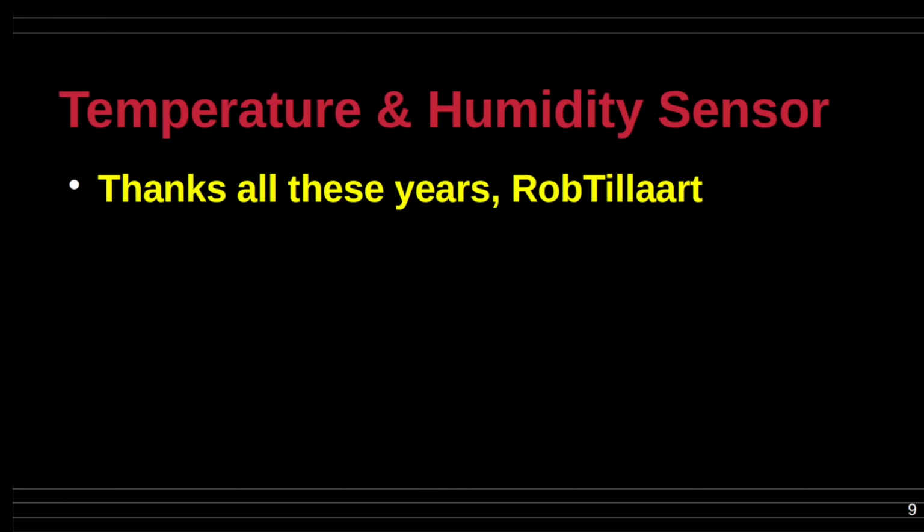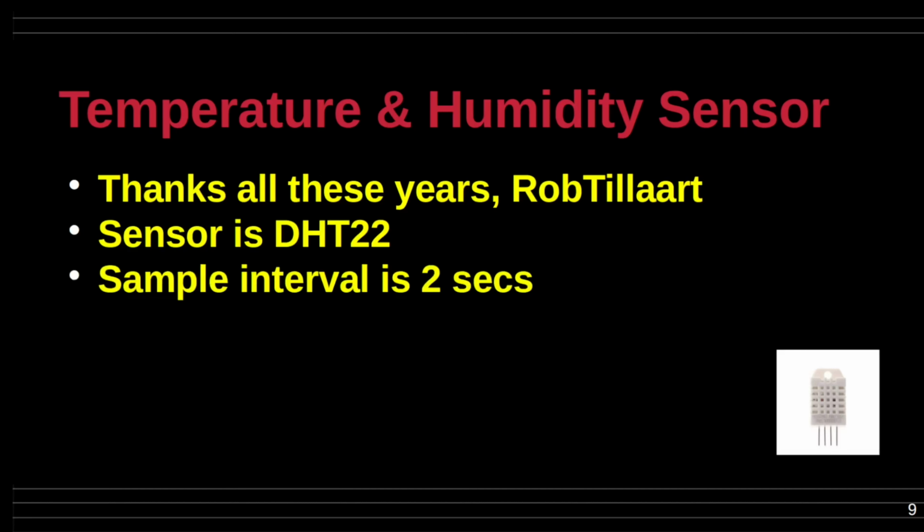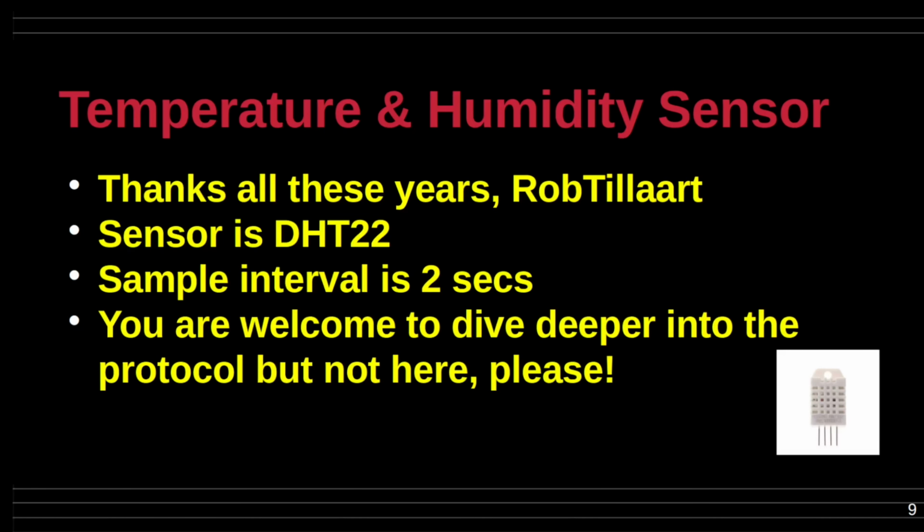The DHT11 and DHT22 sensors have been in use for a very long time. The low cost of these sensors with reasonable accuracy in data acquisition permits their use in many industrial applications. These sensors are not limited to lab experiments. The minimum sample interval for DHT11 is 1 second, and for DHT22 it is 2 seconds.